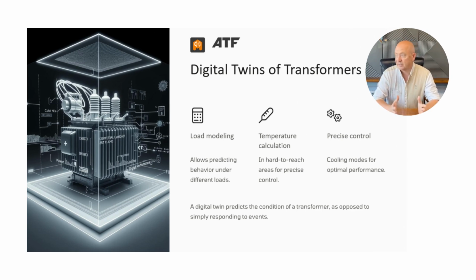A digital twin is a real-time mathematical model of the transformer, built using sensor data and analytical algorithms. It allows engineers to simulate transformer operation under different loads, estimate temperatures in hard-to-reach areas, and control the cooling system with higher precision. Unlike traditional monitoring, a digital twin predicts problems instead of simply reacting to them.